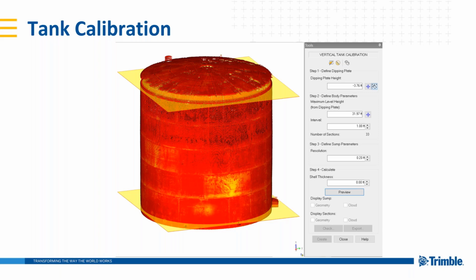Now, we do have the ability to enter a shell thickness. However, we're not so sophisticated that you can put in different shell thicknesses. I understand that you'll have different thicknesses as you go up the tank. In this case, you would probably have to figure out an average if you wanted to do this. This would only be considered if you scanned the tank from the outside. We would assume most people doing a volume calibration would be scanning from the inside, in which case you really don't need to worry about the shell thickness.